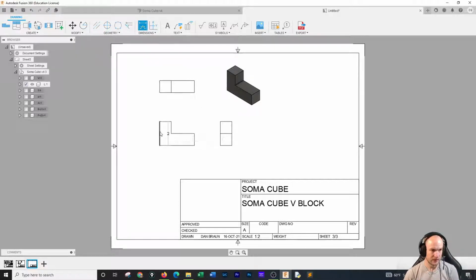Once again, this is the contoured view, so we would have the dimensions on the contoured view because that is the proper procedure. So both the height and the width on this one, and then just so I am not discriminating against the top view, I will put the dimension for the depth on the top view. So right here, and once again, we prefer that to be on the inside instead of the outside.